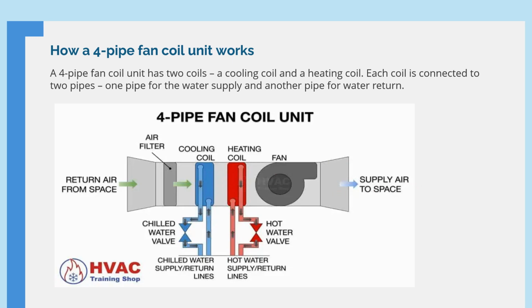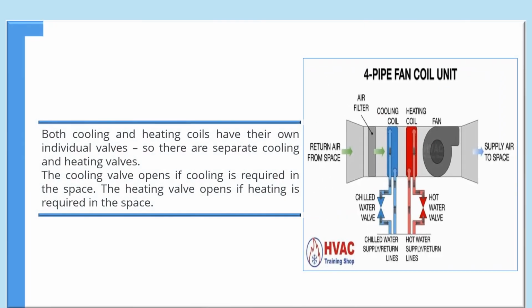Both cooling and heating coils have their own individual valves. So there are separate cooling and heating valves. The cooling valve opens if cooling is required in the space. The heating valve opens if heating is required in the space.